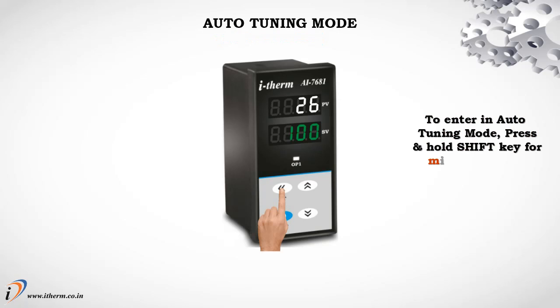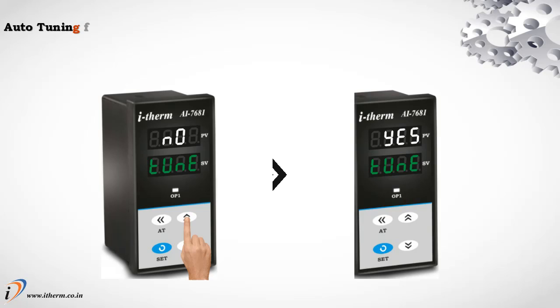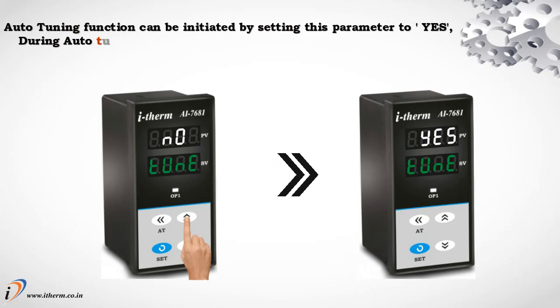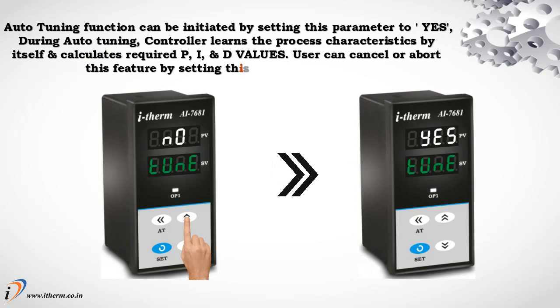Auto-tuning mode. To enter in auto-tuning mode, press and hold shift key for minimum 3 seconds. This parameter will appear only if selected control action is PID. By default, auto-tuning function is not initiated. Its default value is no. Auto-tuning function can be initiated by setting this parameter to yes. During auto-tuning, controller learns the process characteristics by itself and calculates required P, I, and D values. User can cancel or abort this feature by setting this parameter to no.